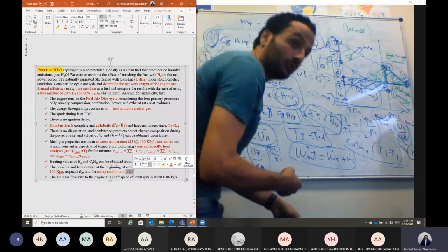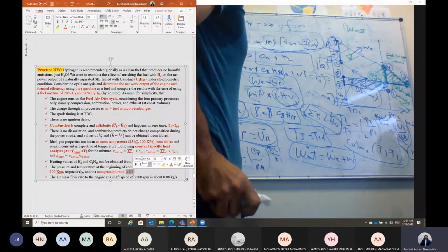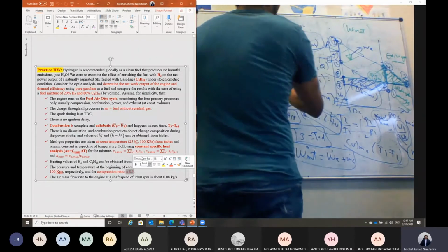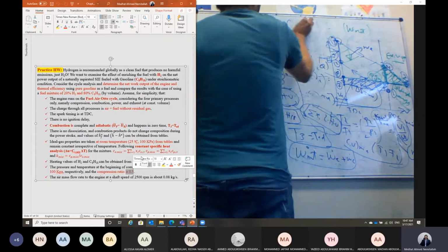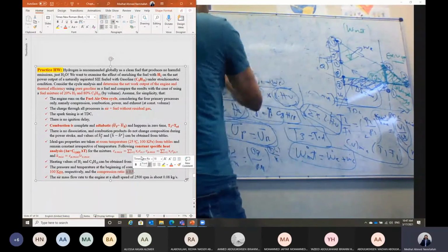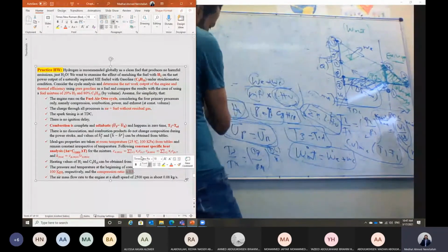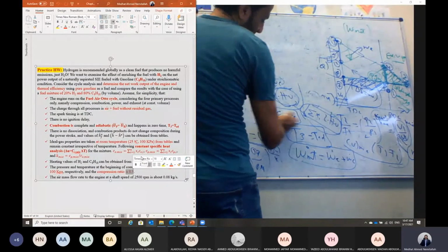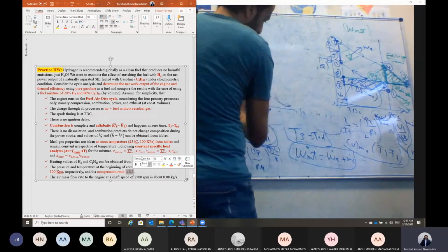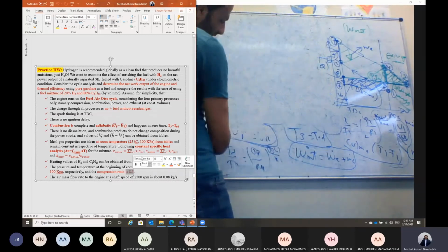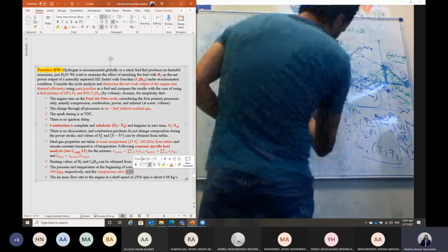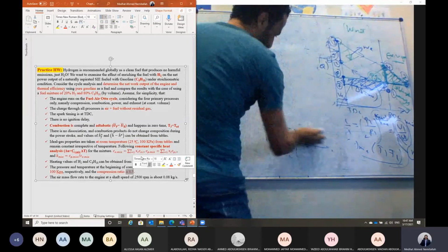And also we can see the effect of hydrogen, which is a very important parameter in the analysis. In all future engines, actually, hydrogen is the future fuel. But usually hydrogen in an internal combustion engine does not result in much addition. When we use hydrogen in the fuel cell, inshallah we'll be talking about this in the last chapter, it can result in an efficiency of about 60%. Here, in the internal combustion engine, the efficiency is around a maximum of 35%.